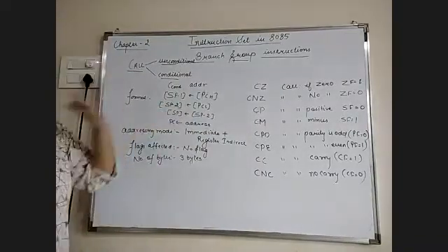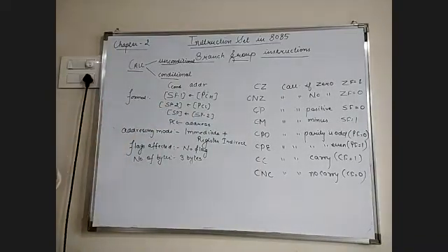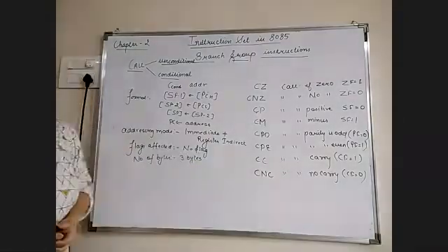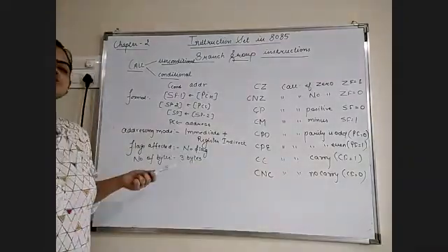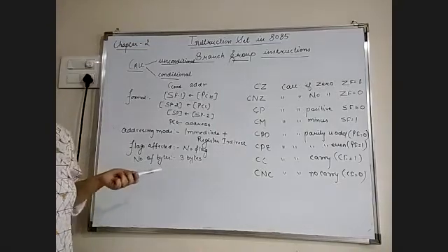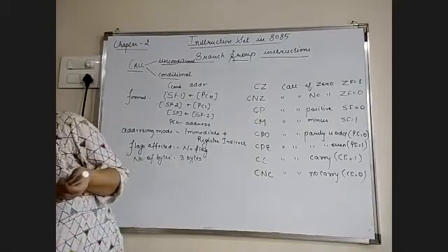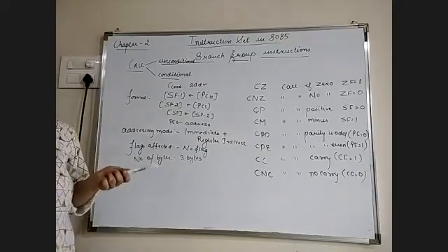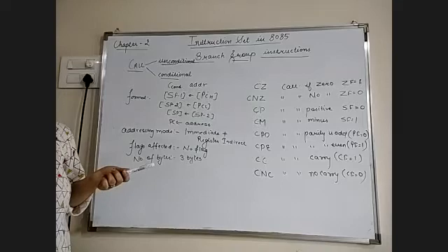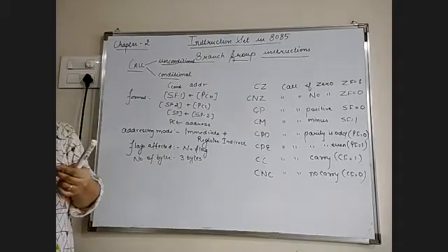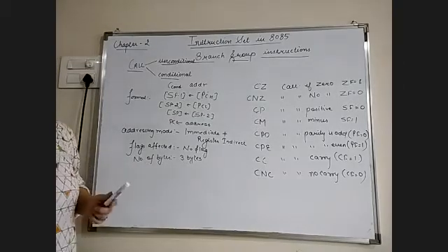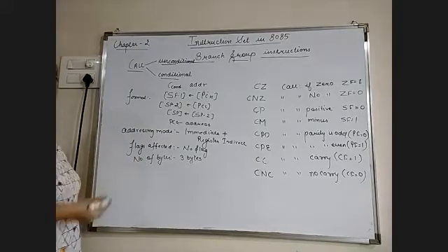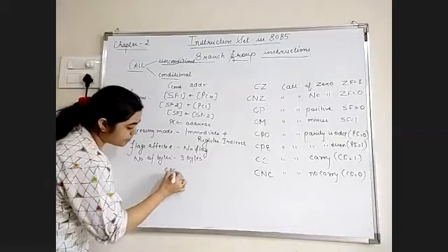So the rest of the statements are the same; in the case of jump we just replace it with the call statement. In case of jump, the microprocessor can jump to a memory location which is also part of the main program, but in the call statement the microprocessor jumps to a memory location which is not part of the main program, which is the subroutine or subprogram. So this is about the conditional call statement, and we can see one example.